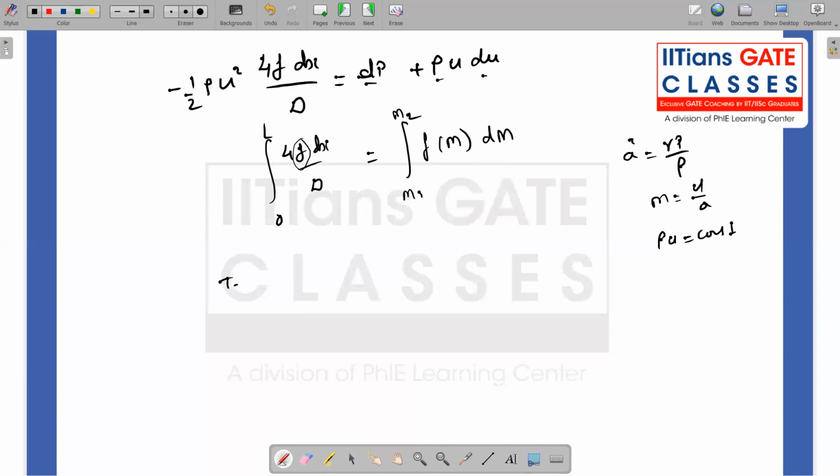Okay. So now, the other properties are simple. The change in T2 by T1, you can always get using the energy equation, P2 by P1, rho 2 by rho 1. They are all a similar procedure to what we have done for the flow with heat addition. Only the effect of friction is given in an integral form as a function of Mach number, where you have to solve the integral. And again, I'm stressing that f is not trivial because it's an empirical relation.